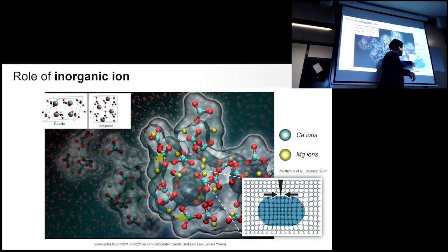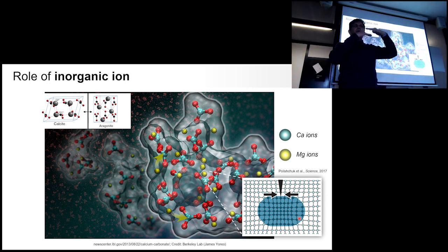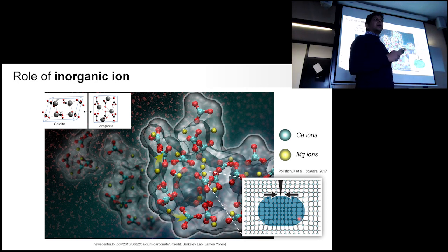Here, instead, these tiny atoms sit and stretch the lattice planes, so there is some local tension and compression going on across the planes, and that's another way you can make the crystal stiffer.